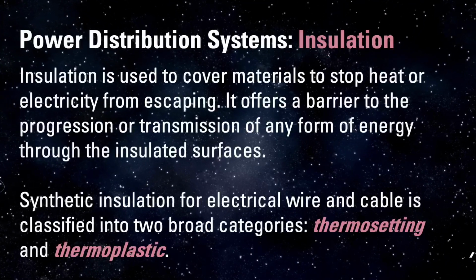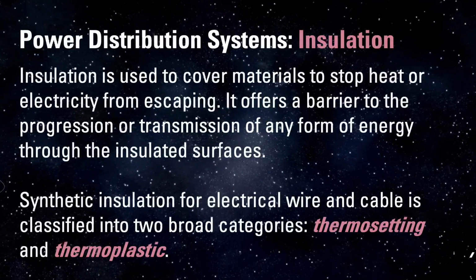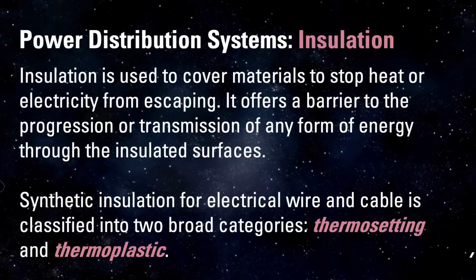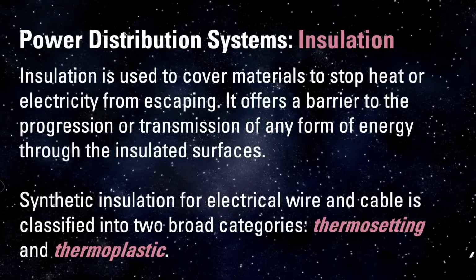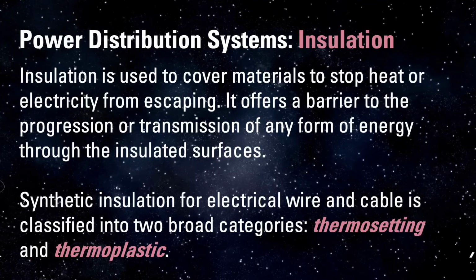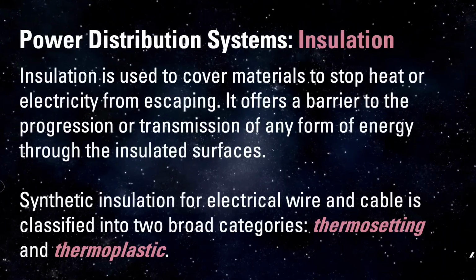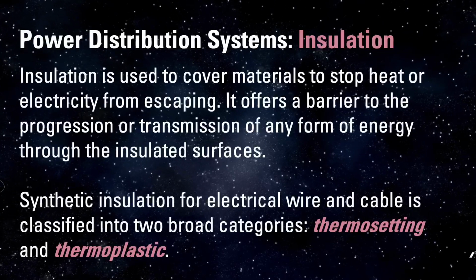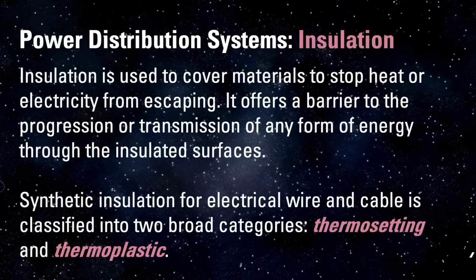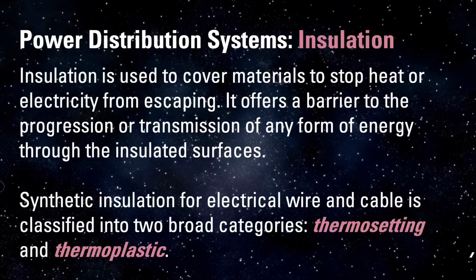Thermosetting insulation has a higher tolerance to higher temperatures compared to thermoplastic insulation. Thermoplastic insulators have a high risk of heat deformation at inappropriately hot temperatures. Thermosetting insulation has superior flexibility, which it can retain in cold temperatures.